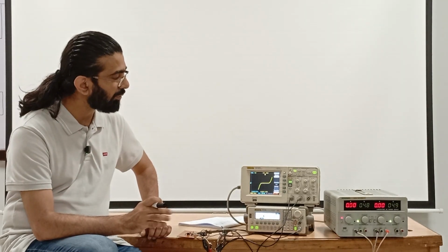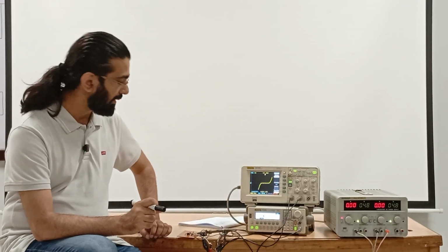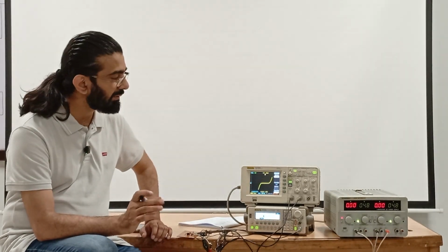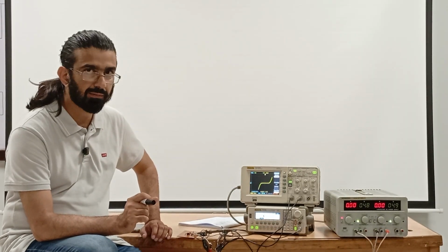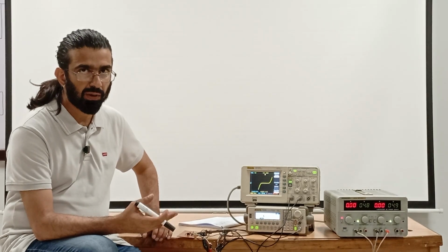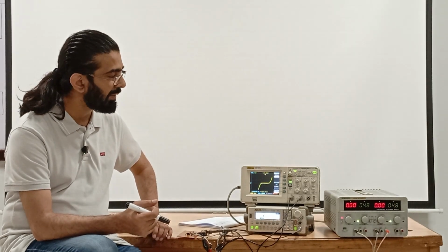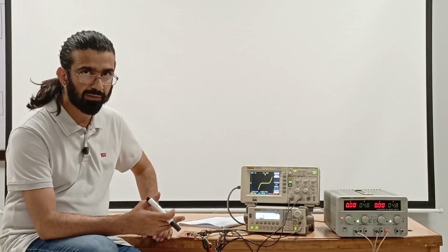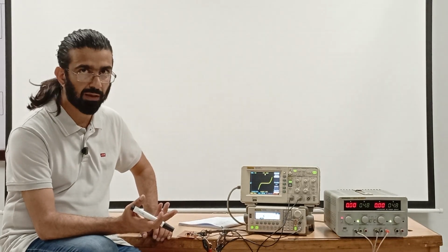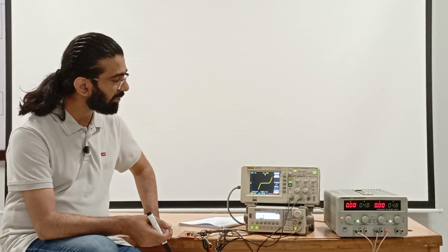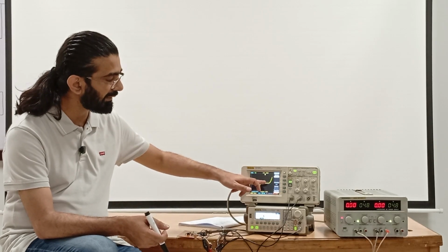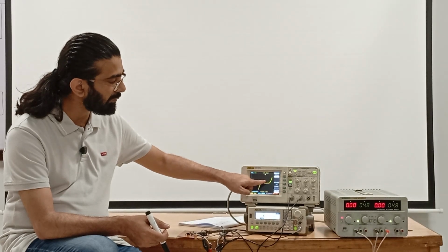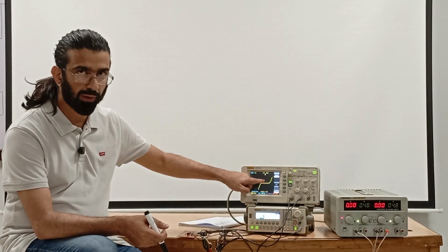And in terms of signals and systems, we would say that it is a system without any memory. It's a memory-less system. And such nonlinearities are very common in electrical systems. For example, in a class B amplifier, crossover distortion has the same type of characteristics where they have a dead zone. One input is changing while the other input doesn't have any effect on the y-axis.